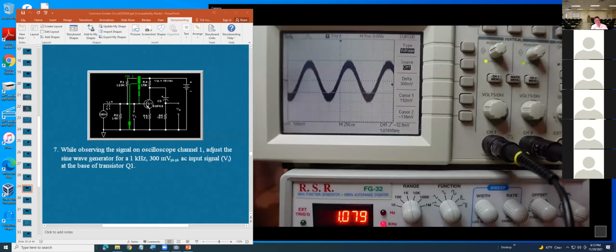But when you see the signal is not clear on the oscilloscope, then don't use the automatic measurement. You must be using the cursor. That's the key point for the guy to get the lab done.